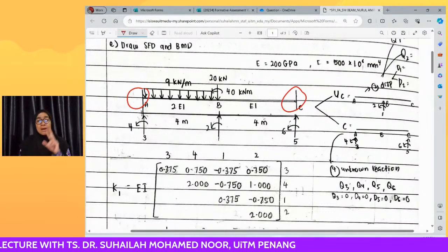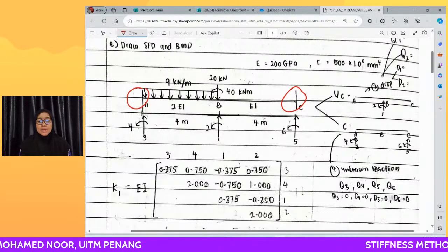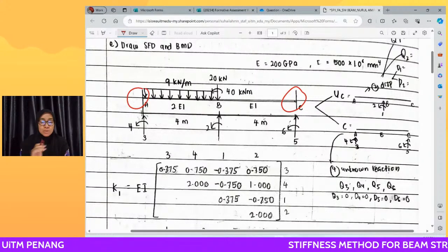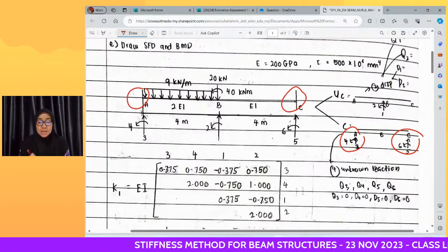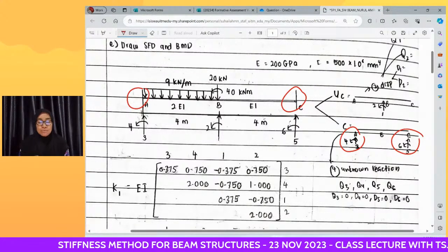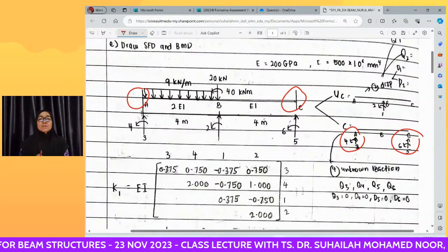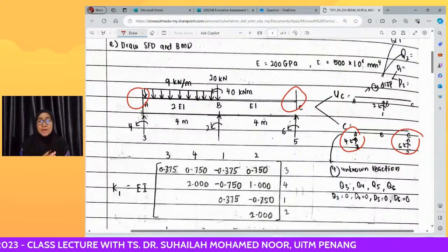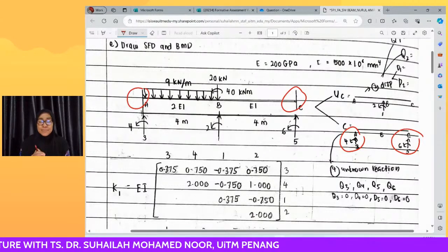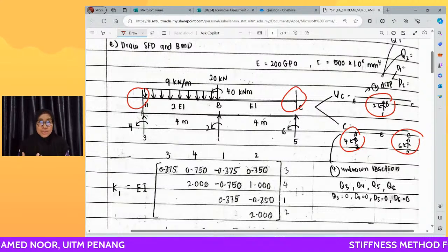So we only count 2 in the Y and Z components: 2 at A and 2 at C, so 4 degrees of freedom in the constrained system. Since there are three nodes A, B, C, in total there are 6, so the remaining 2 we put at B in the unconstrained system.